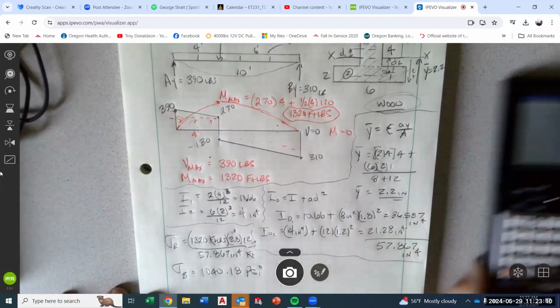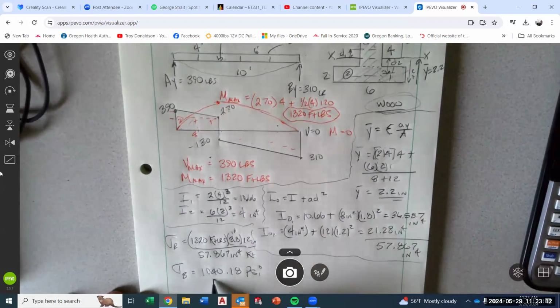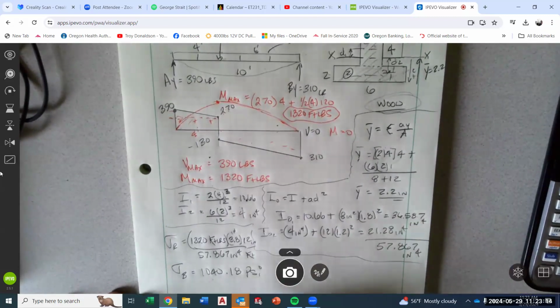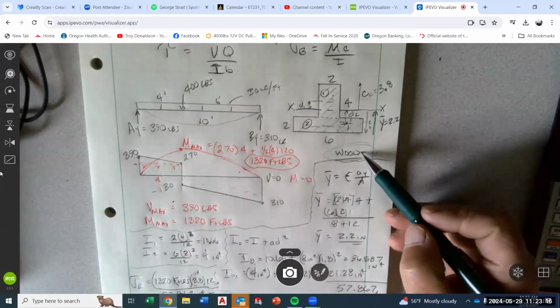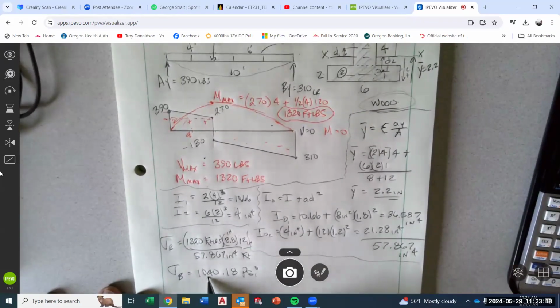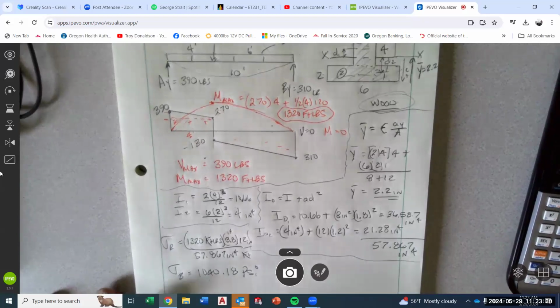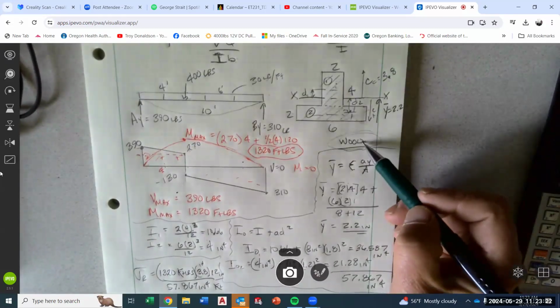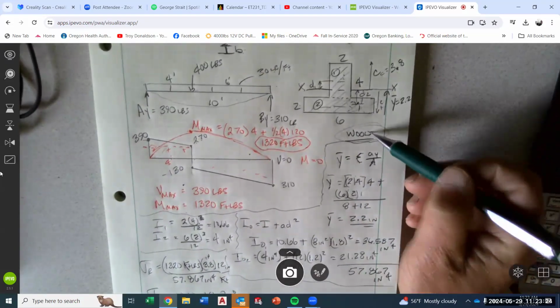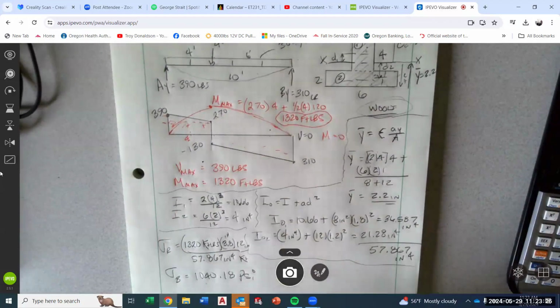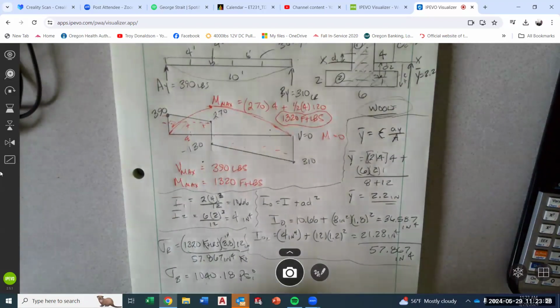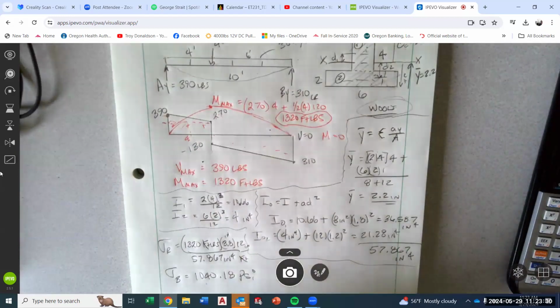Now I just made this problem up, and I actually came pretty close to acceptable bending stress. Doug fir is 900, so we're close for this to work. Maybe I choose a harder wood with a bending stress of 1020 and it works, kind of thing. So we're going to say it works. If your bending stress is good, then you would check your shear stress.